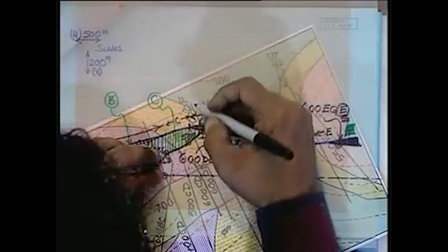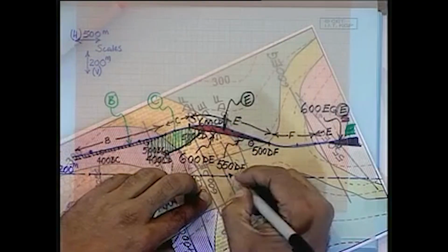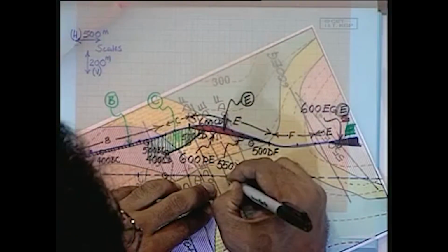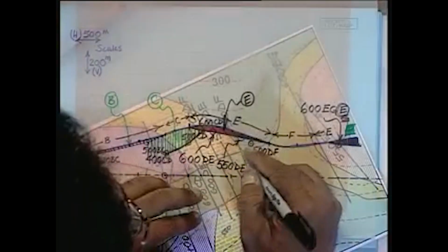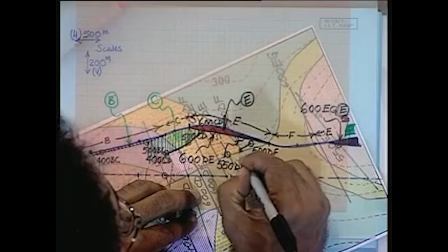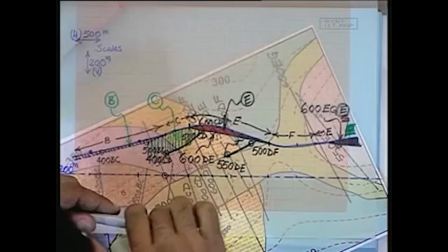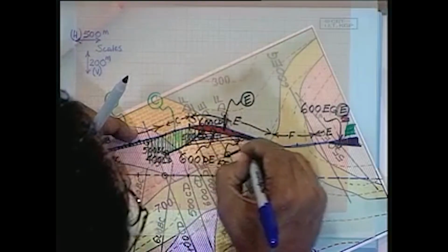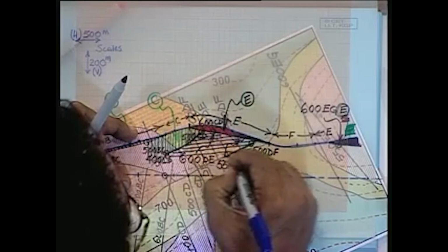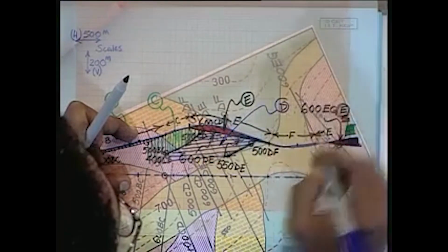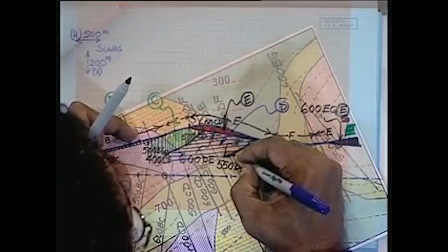and we have got another interface, another strike line corresponding to the interface between D and F, and that is this one. This is at elevation 400. So we come to a point here, so that is going to give us the interface between units D and F. So above this one is going to be unit D, and underneath this one is going to be unit F. So this one is going to be our unit D, and underneath this one is going to be unit F.